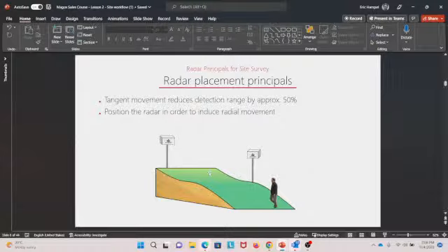So if you have the chance to identify the targeted direction of people coming to site, or whatever the reason for the given direction is, as much as you can, make sure that the expected movement that we want to capture is towards or away from the radar, rather than parallel as indicated with this one. So the person walking uphill here will be much harder for this radar to detect compared to this position. Just make sure, and that's something that is absolutely crucial.